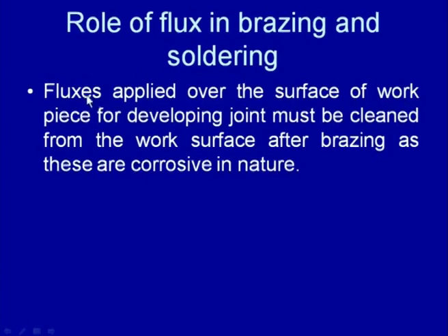joint. The fluxes applied over the surface of the workpiece for developing the joint must be cleaned from the surface of the workpiece after the brazing, because these fluxes present on the surface of the workpiece are found to be corrosive in nature. Therefore, once the fluxes are applied, these must be removed from the surface.